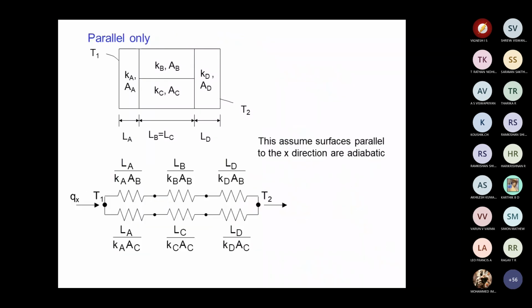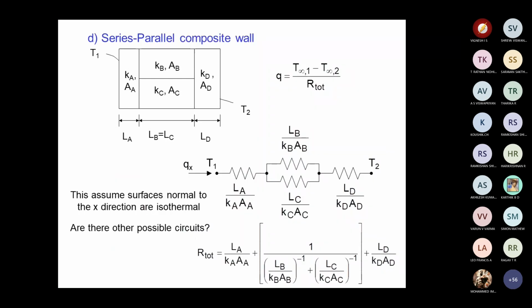T1 is the outside temperature, sir. T1 is the inner temperature and T2 is the outer temperature. Okay, finally del T is the one. Suppose the del T comes in minus, as in our assumption we assume heat is transferred from left to right, then automatically if del T comes in minus, the heat transfer is from right to left.